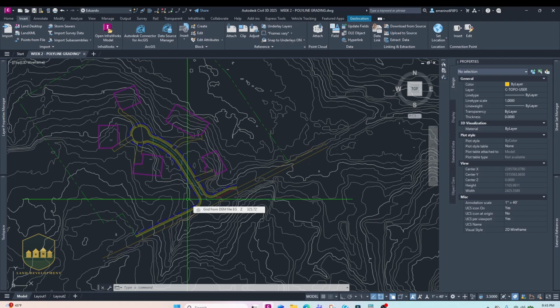The manual tools are, for example, polylines, adding a boundary, pasting surfaces, and so on. Automation tools, I would consider corridors, feature lines, grading groups, and these tools do the grading for you by just selecting a few buttons. It'll draw out contours for you.